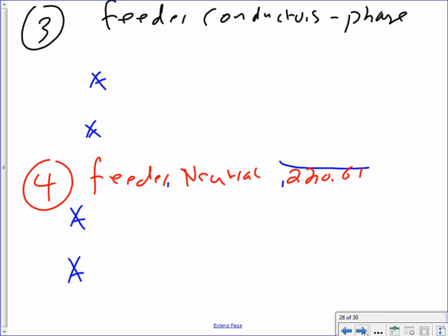I'm going to size my conductors, and my conductors have to match the overcurrent protection device. Do you have to match the overcurrent protection device? No. Up to 800 amp, your overcurrent protection device can match your load amp, but always match the overcurrent protection device as a designer. So we take the 350, gentlemen. 450.